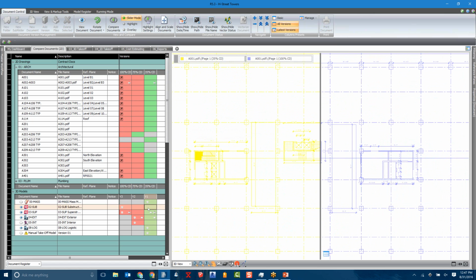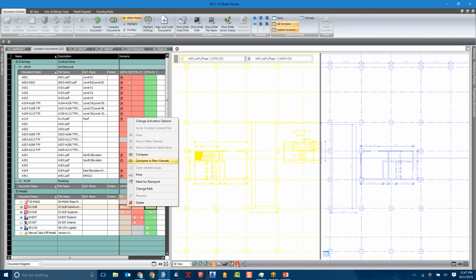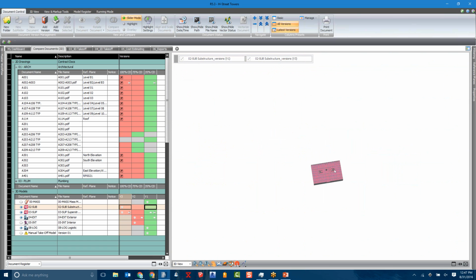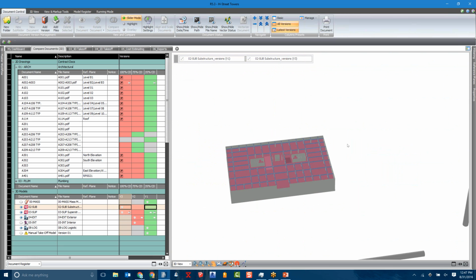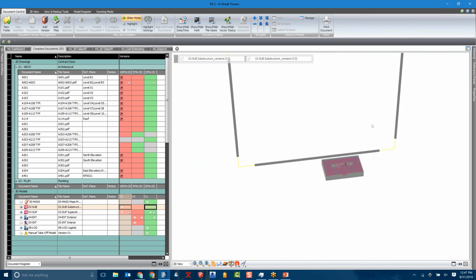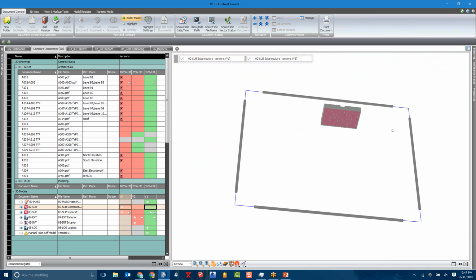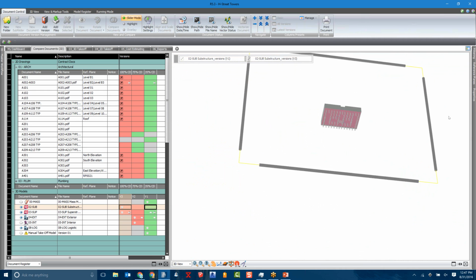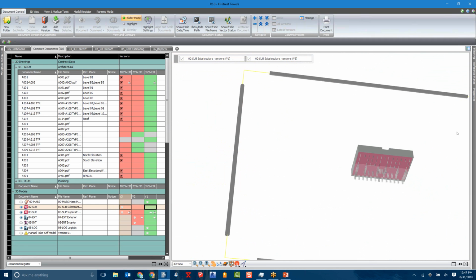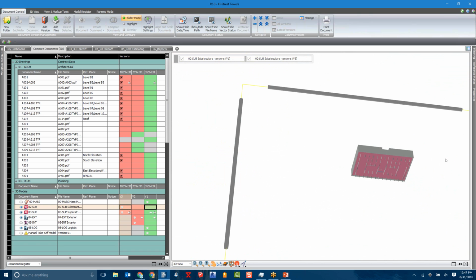And we could do the exact same workflow here with models. So why don't we take a look at our substructure model, since this is the one we'll be working with in our estimate. We can rotate around a little bit and grab our node, and we can start seeing what the differences are. This particular one doesn't seem to have drastic changes other than maybe the piles. So if I grab my slider, I can see that the piles have been reduced significantly.